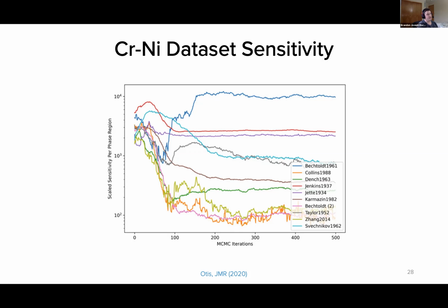So you can add those in for the chromium unary and treat them as degrees of freedom, and then optimize those to the data that's available for the chromium melting point, as well as all the chromium thermochemical data for the solid phases and the liquid phase. And you could inform yourself on the uncertainty and also the sensitivity as well.